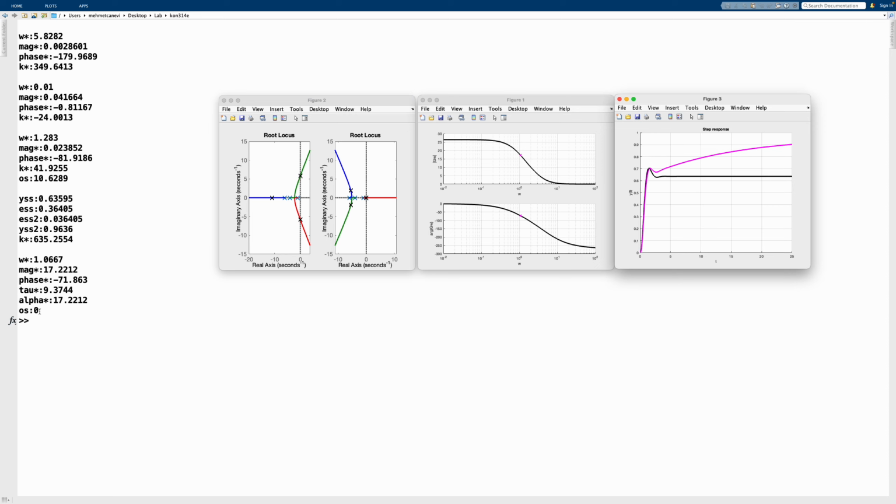And you can see it says overshoot is 0, which is practically correct by measurement, but in terms of shape, it's something different from what we expect. If you want to have 10% overshoot, you would like to have something like this. So this behavior, but it should be amplified so that it has the steady state error that is requested here.